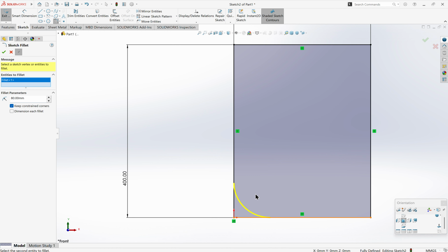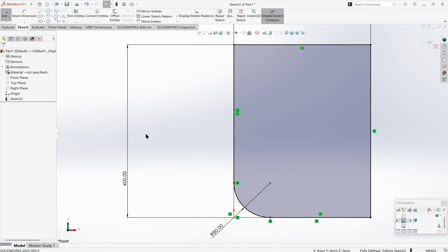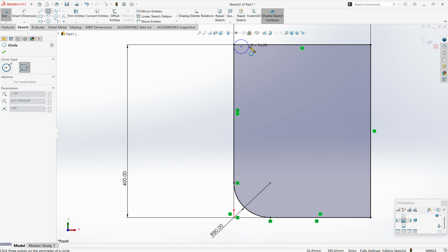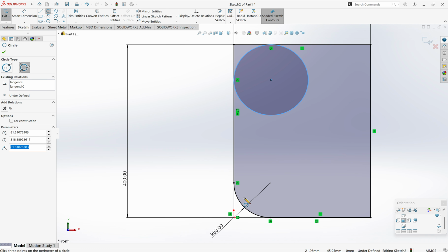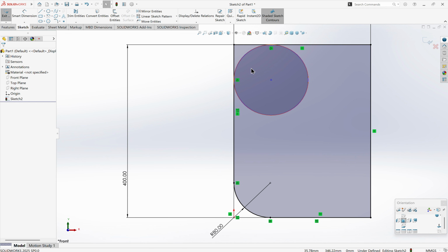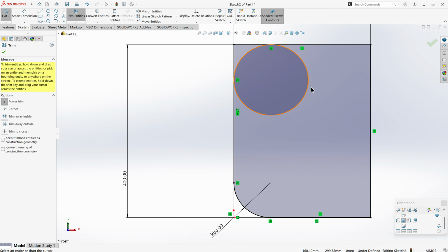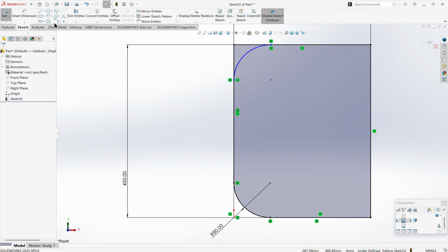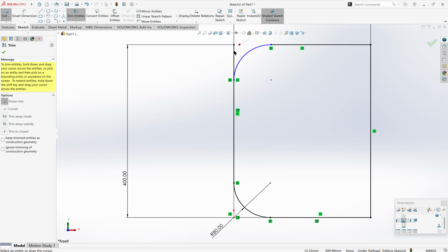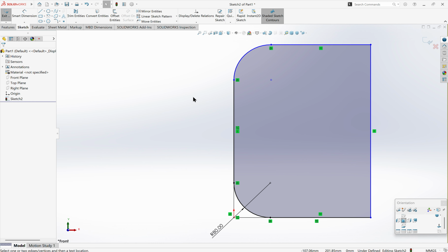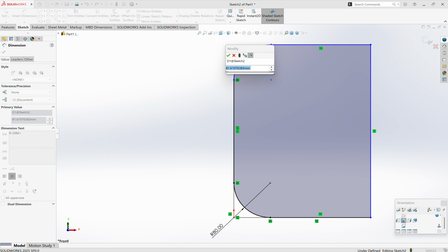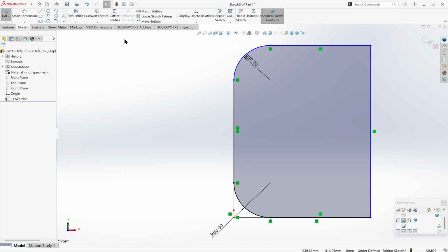You just click on here and it's going to make it a round edge. Okay. So let me check this, the parameter circle. If we click it on here and then click it on here, yeah. And instead of this, if the fillet tool is not working, just choose this and then trim entities and cut it like this. Okay, it's on par. Yeah, cut this and then cut these two. Yeah, basically the same. Give it as 80. And we did the same thing but with one click with the fillet tool. Okay, that would be easier.